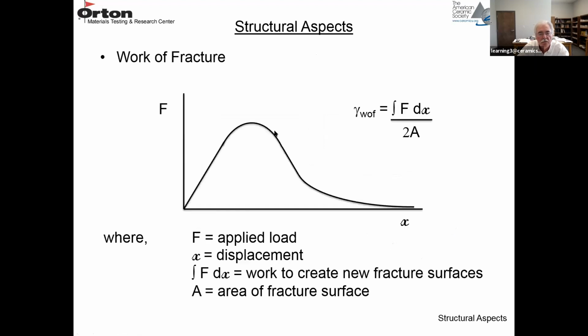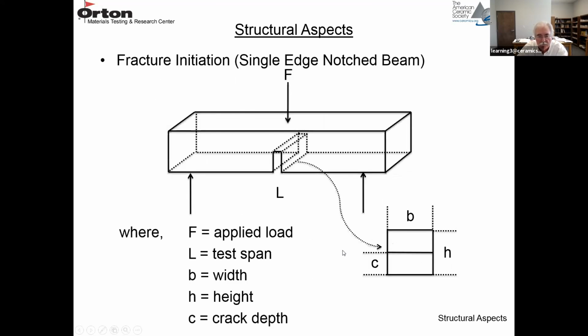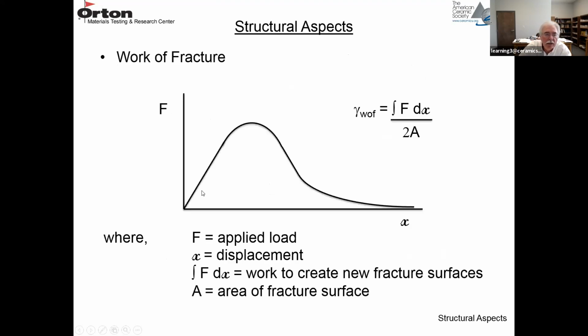So what you do is you fracture this in a very slow manner. In the previous sample, you fracture it rather quickly at a fairly high rate of speed because you want catastrophic failure. In this experiment, you fracture it at a very slow speed to get a stable fracture. So force, or load, versus displacement X. You load it, then the crack starts growing in a very stable manner. And the longer this tail, the more crack bridging in the wake of the crack.